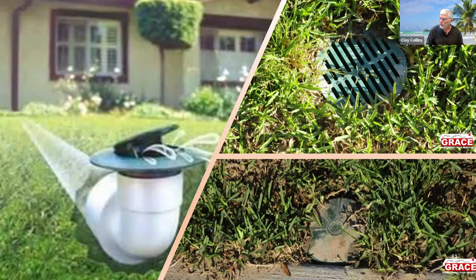Is there a time frame that I tell my clients to allow for water to drain to determine if there's poor drainage? I think water should be gone from the house in about 4 hours after it has stopped raining. That should be enough for water to run out. Think about draining a bathtub. That's an awful lot of water. Now, yeah, the ground is going to absorb some of it. How much it absorbs depends on how long it has rained. So a first rain in a dry summer, 4 hours. If it's been raining for a long time, it's anyone's guess.